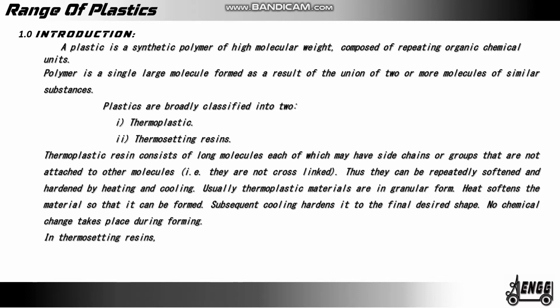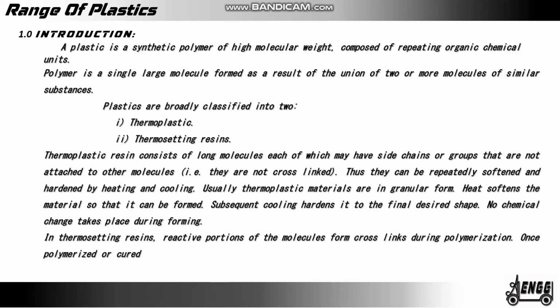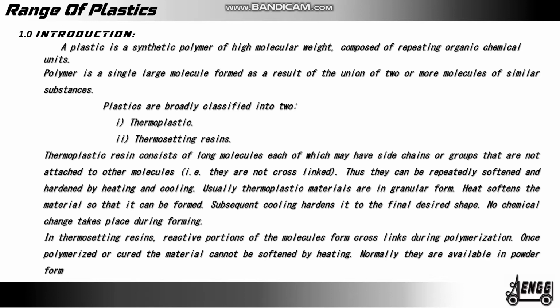In thermosetting resins, reactive portions of the molecules form cross-links during polymerization. Once polymerized or cured, the material cannot be softened by heat. Normally, they are available in powder form and are cured in the mold at high pressure and temperature. As technology progresses, the line between thermoplastics and thermosets has become less distinct.